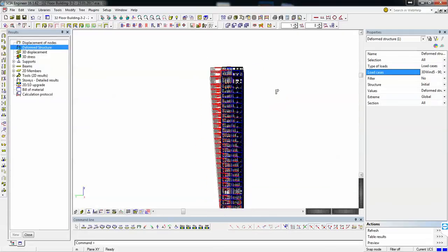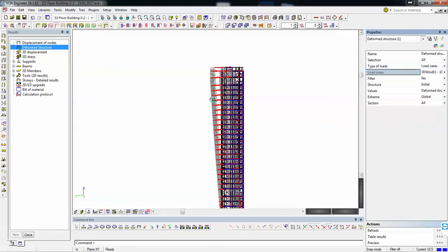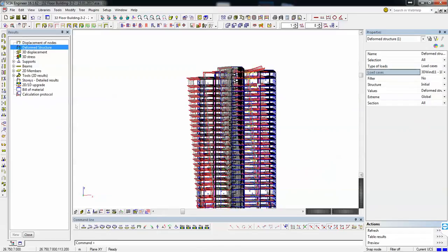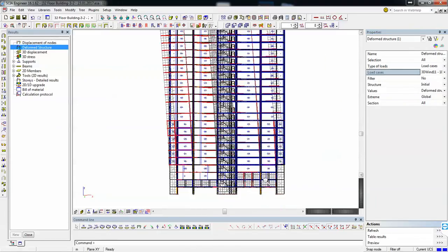I need to evaluate this also in combination with other loads, which can help the structure, because just loading horizontally like this is really conservative, since we don't have the self weight or other vertical loads acting.